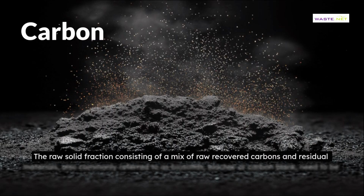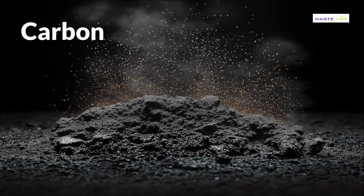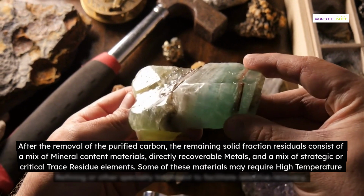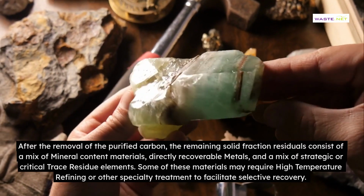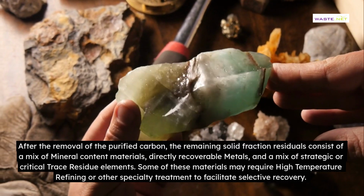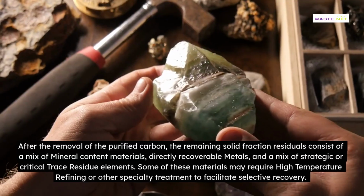The raw solid fraction, consisting of a mix of raw recovered carbons and residual materials, also commonly referred to as biosolids, biochar or carbon black, need to be further processed in order to recover a purified carbon product. After the removal of the purified carbon, the remaining solid fraction residuals consist of a mix of mineral content materials, directly recoverable metals, and a mix of strategic or critical trace residue elements. Some of these materials may require high-temperature refining or other specialty treatment to facilitate selective recovery.